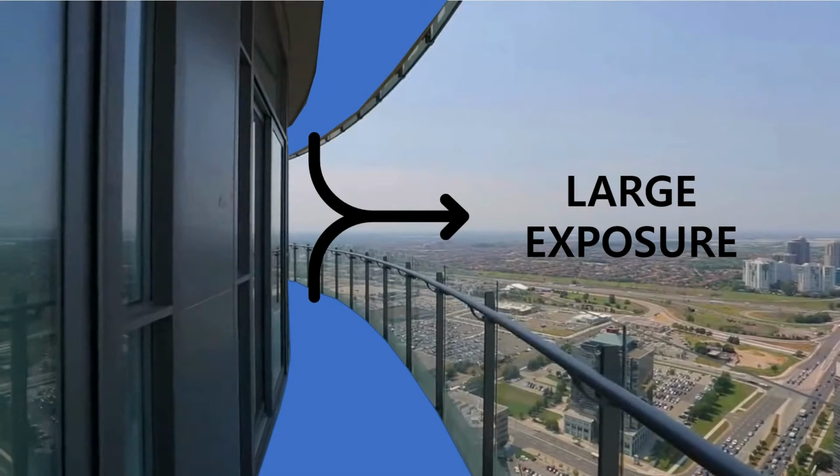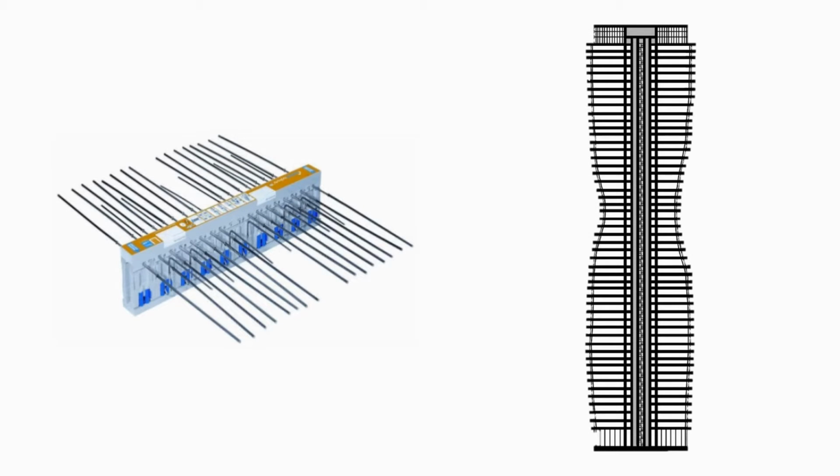Secondly, there was a significant problem regarding the insulation due to the balconies. Thus, we introduced two solutions to the heat transfer problem: the installation of thermal breaks and the internal bulkhead with external insulated soffit.